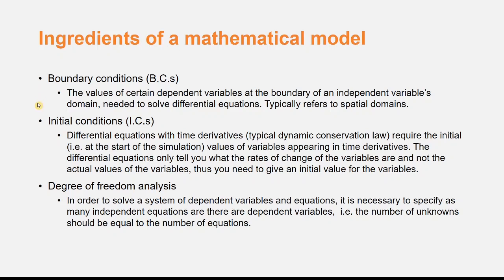Differential equations with temporal derivatives also require initial conditions, which are values of the variables appearing in the derivatives at some initial time, usually a time equal to 0. Finally, it can be useful to perform a degree of freedom analysis on the model to determine how many independent specifications can be made in order to solve the equations. As well as determining how many degrees of freedom there are, it is useful to define which sets of variables are sensible specifications.